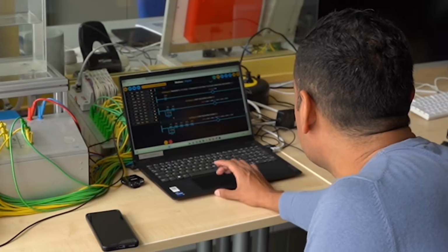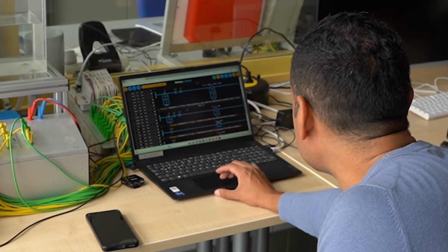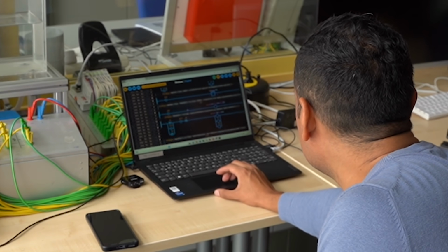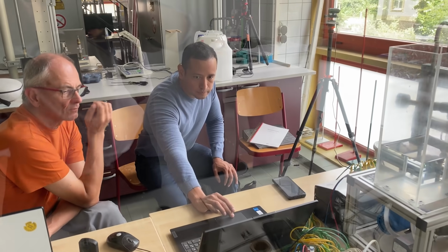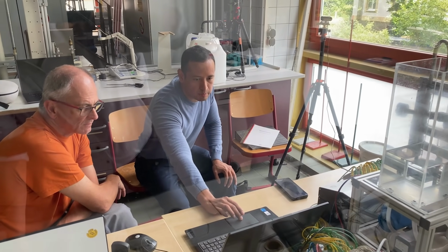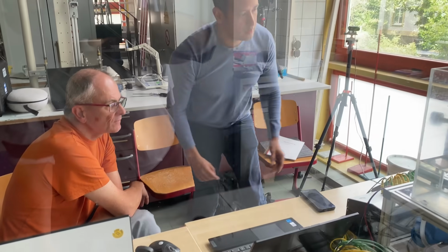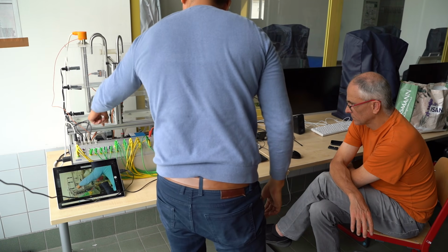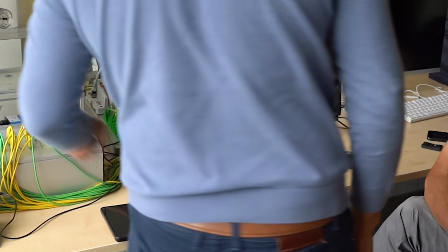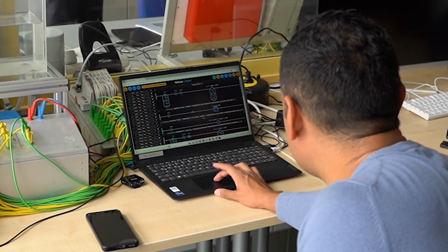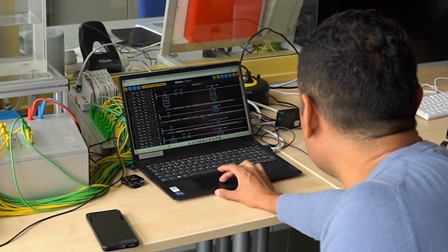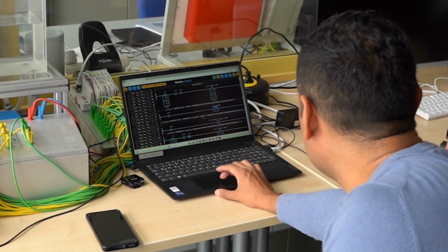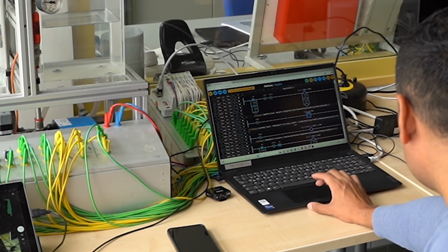So what I'm going to do now is, for instance, this instruction is seen here. Here is the explanation. This is part of the heating cycle. The heating cycle is just this recirculation pump that passes through the heater and then comes back. So it says in the heating cycle, this is safety. If the sensor B3 is on, then there is water at minimum level at T1. But if it's off, then there's nothing, so it won't start.